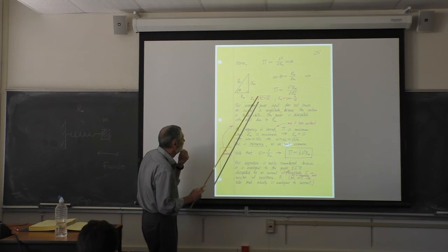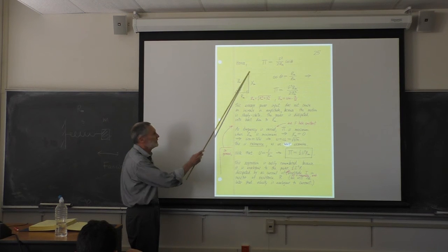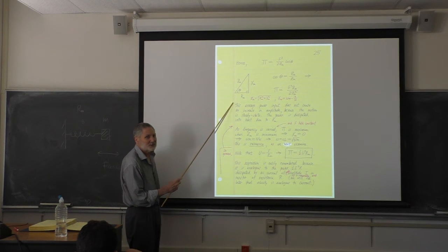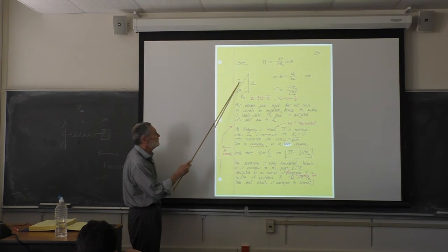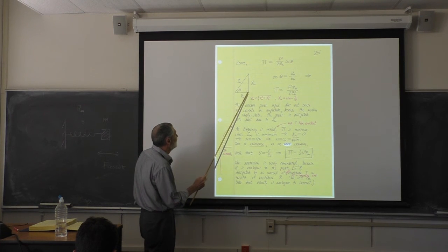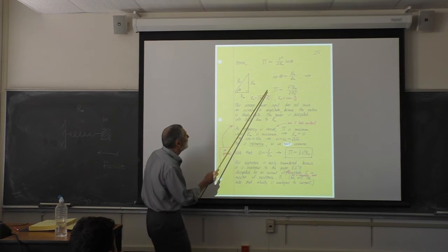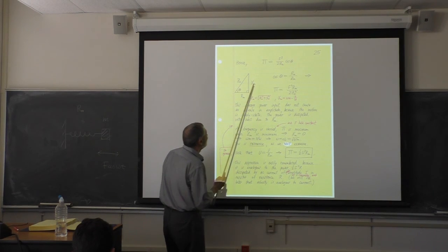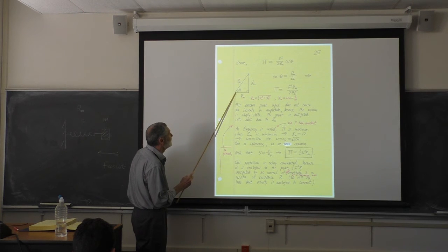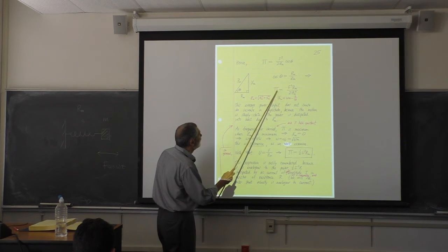First of all, remember theta. Remember our right triangle. Here it is. Use this a lot. Here's the magnitude of the impedance. We're in the complex plane here, if you like. This is the real part of the impedance and the imaginary part, the resistance and the reactance. So I need the cosine of theta here. Well, I can see that the cosine theta is going to be the resistance divided by the magnitude of the impedance. So I get this.